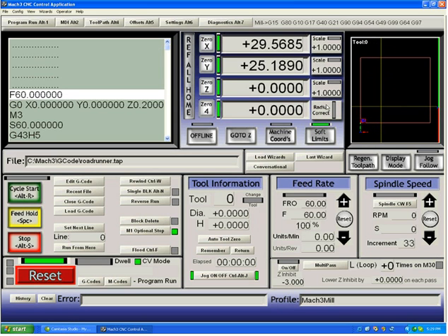Now, by zeroing at a particular spot, by pressing the 0 buttons, and then regenning the toolpath, you'll see my crosshairs are showing 0 position is right where my Roadrunner is now located, off center from the home switches and where I placed it on the mill. This is a very typical way of cutting.